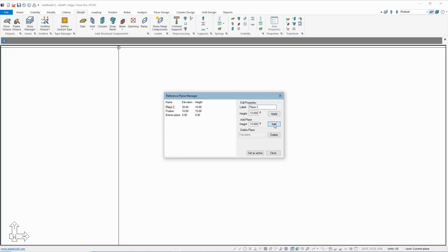So we'll go ahead and add a few more planes here. These will be essentially the planes where we reference the different bearing walls for the system. Let me go ahead and change those so we have the right plane structure. Okay, all of our levels are 10 feet.